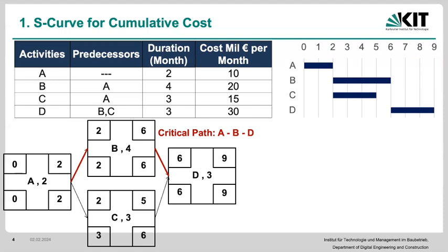Yeah, without anything about the duration of the total project changing. That's the whole point. A critical activity in the CPM, or the critical path method, belongs to activities that, if they move somehow, or if they, let's say, increase in their duration, the total project's duration would actually increase. That's how we basically talk about it. And when we formulate it, that's by means of the total float, which was a function of the early start and the late start, or the early finish and the late finish, okay?